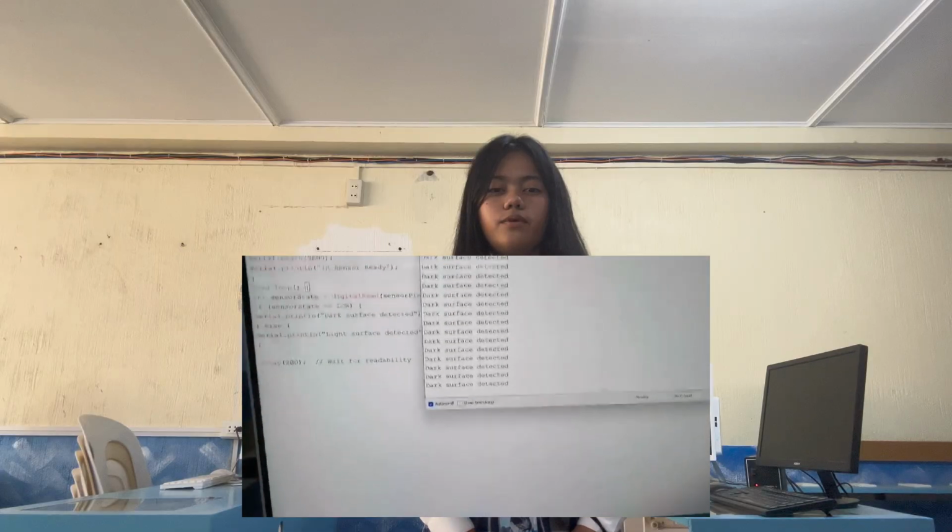The proximity sensor detects nearby or distant objects using infrared light. It includes an IR LED and a photoresistor and is widely used in security, mobile devices, robotics, and automation. In the first activity, we use an IR sensor with an Arduino Uno, breadboard, wires, and a black mouse pad to observe how surface color affects infrared reflectivity, comparing black and white surface via digital output.